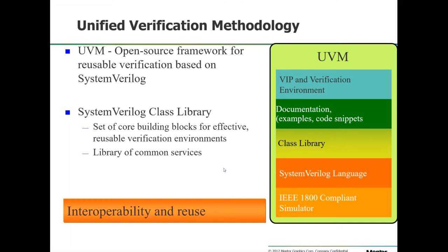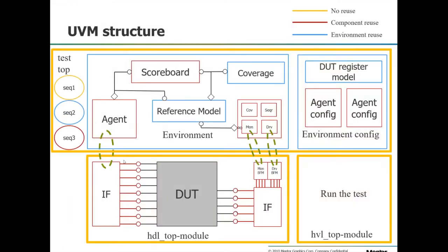So you want to make sure that it works on every SystemVerilog compliant simulator, and you want to make sure that any objects that you create are reusable in different phases. So the base object of a UVM test bench is called an agent.